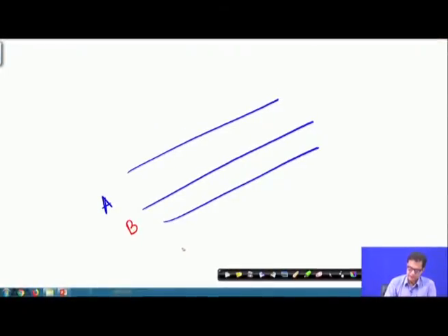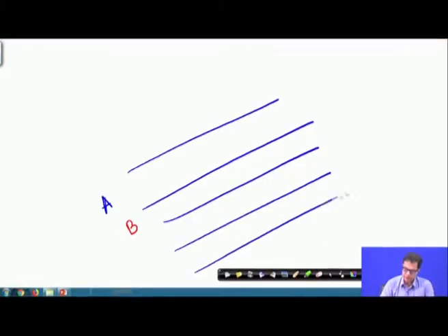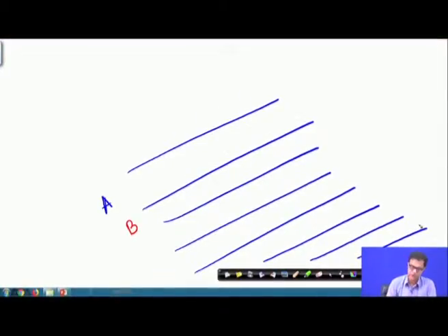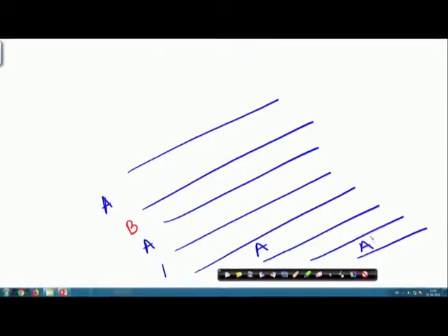So, we said that while arranging them in a plate fin configuration, we usually put them in alternate hot and cold condition, in a sequence like A, B, A, B, and we always try to put a symmetry in this pattern.